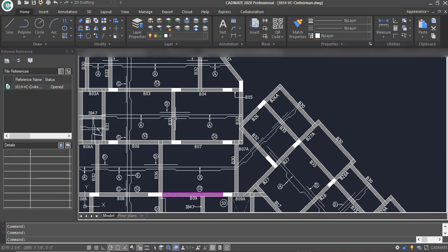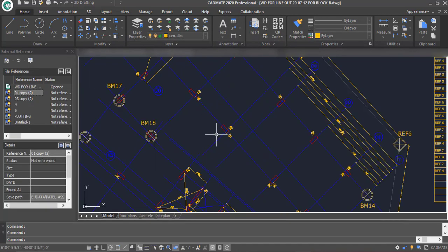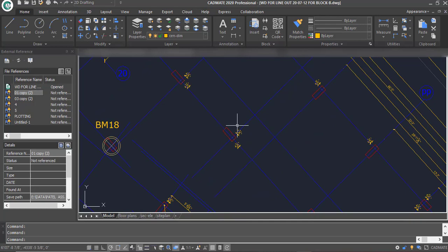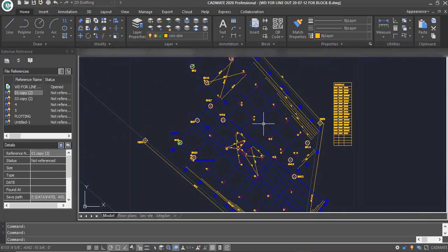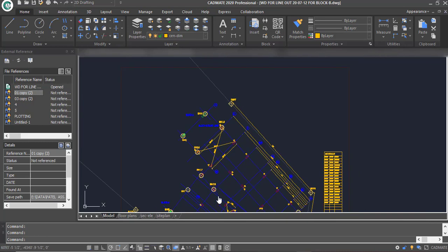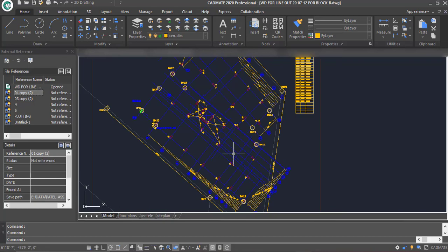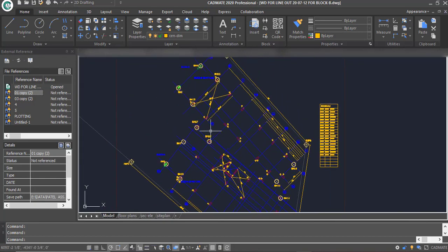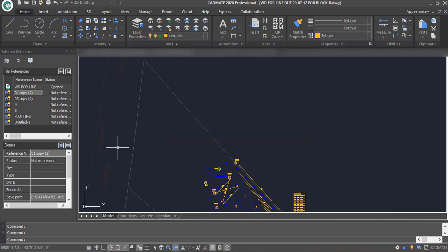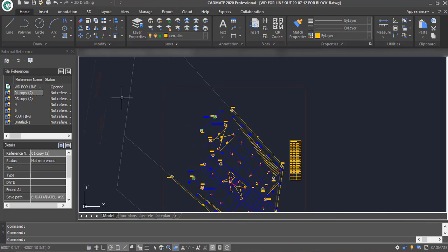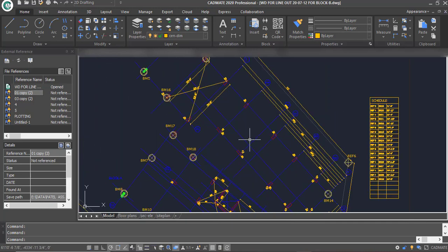In order to develop this detail, we require the architectural drawing input as well, where the column orientations, distance between two columns, grid to grid dimensions, orientation, everything matters, right? As you can see, this building has quite an irregular shape. Based on the northing, you can see the road details are also provided over here with respect to the plot area. So all these details matter.